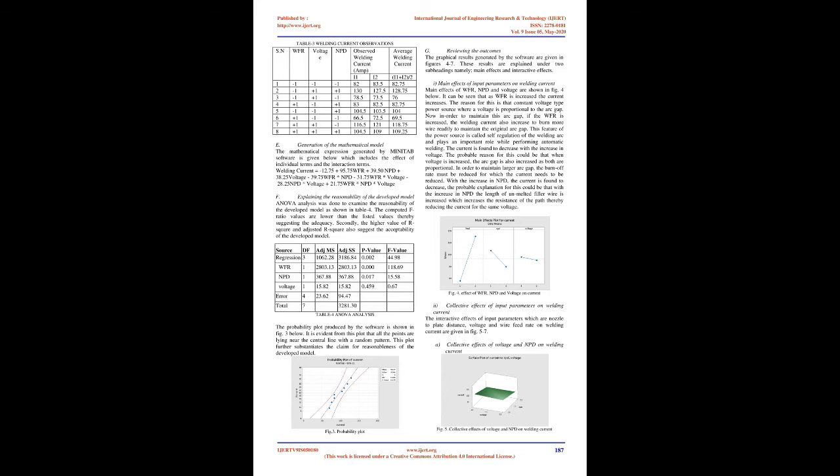C. Establishment of a design matrix. The design matrix was developed by Minitab software with a total number of 8 runs in 2 replicates each. The combinations of these 8 runs are given in Table 2. The weld beads laid on different specimens at the combinations given in Table 2 by bead on plate technique are shown in Figure 2 below. Fig 2. Welding beads for different combinations formed by MIG welding.